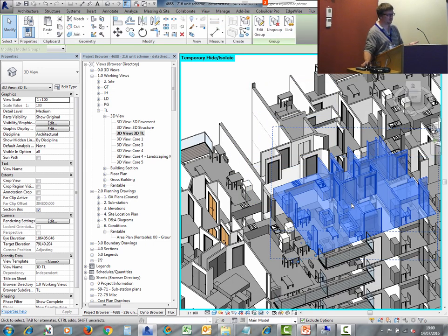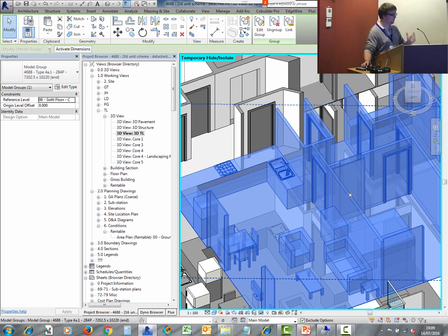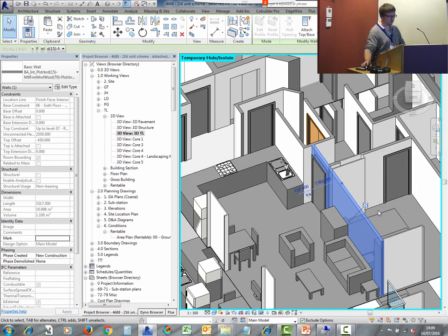So obviously these would have been set up in the same sort of way, so there's sub levels within it. If I pick that wall, it says it's going from 6th floor 0 up to 7th floor. It's got an unconnected height. It might not be how you would model it if you were drawing it in situ, but it doesn't get messed up, if you know what I mean. They don't end up jumping all over the place. But if you end up needing to edit that level that is in the project model, nudge it a bit, the walls will change, will they not?